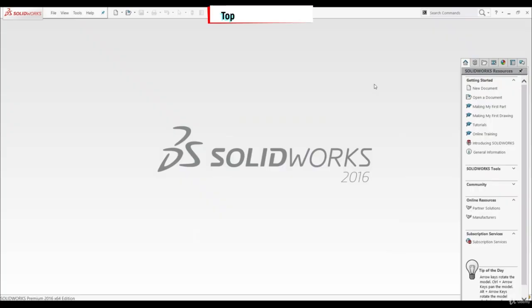We have two ways how we can create an assembly. We can use the traditional bottom-up assembly method, where parts are created separately, then inserted into an assembly document, and then mated together. And then we have a second method to create an assembly, and this is the dynamic top-down assembly method, where parts can be created together in the context of an assembly.